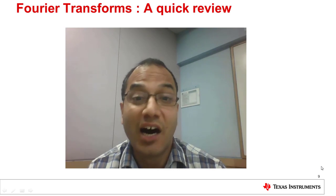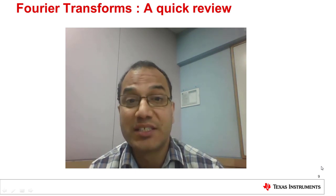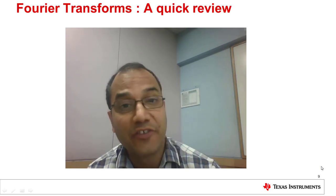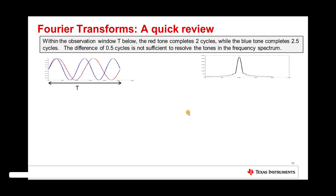Fourier transforms are at the heart of FMCW radar signal processing. As we will see throughout this series of videos, they are used in range, velocity, and angle estimation. So we will from time to time take short detours to remind ourselves of relevant properties of Fourier transforms. A Fourier transform converts a time domain signal into a frequency domain. So a single tone in the time domain produces a single tone in the frequency domain. Likewise, two tones in the time domain should result in two peaks in the frequency domain. But is that always the case?